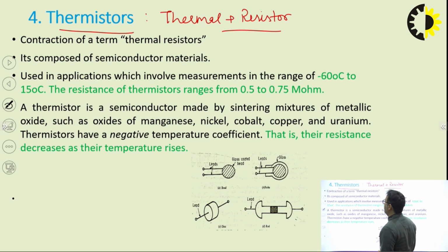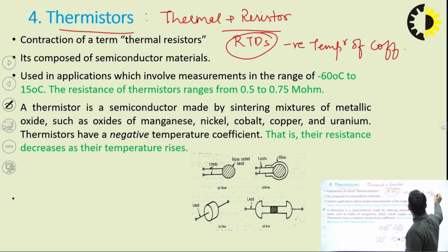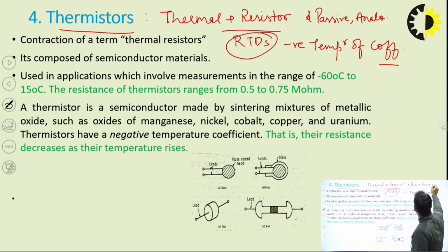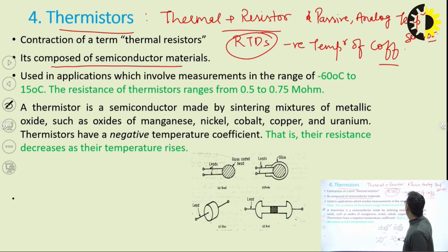It is quite similar to RTDs, but with one difference: they possess a negative temperature coefficient. Rest, their working is similar to RTD, and like RTD, they are also passive analog temperature sensors. They are composed of semiconductor material, obviously because they have a negative temperature coefficient.